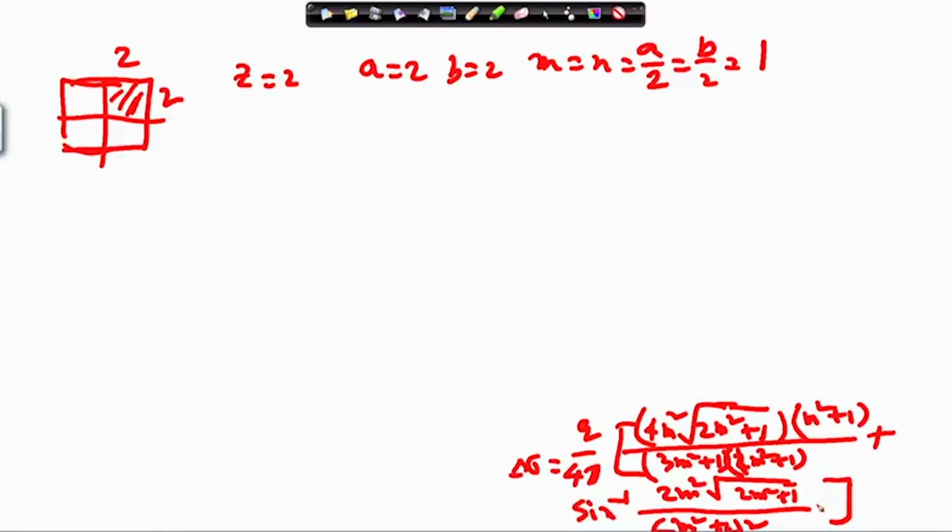So, I have converted, instead of m and n only m is required, because m and n will be equal for all cases. So, this is the formula to be used, and if I use that, then del sigma at 2 meter will come 0.07008 q, that means it will be 175.22.